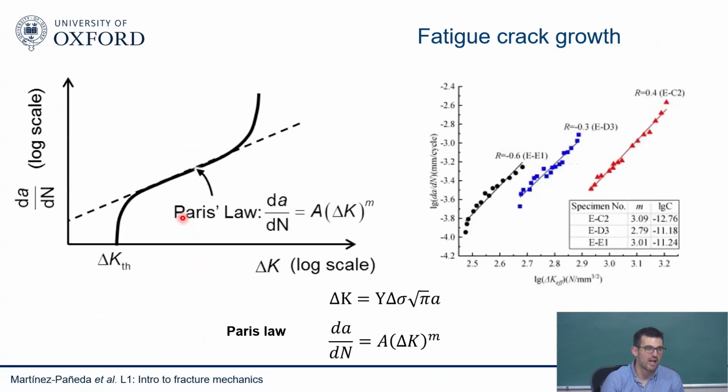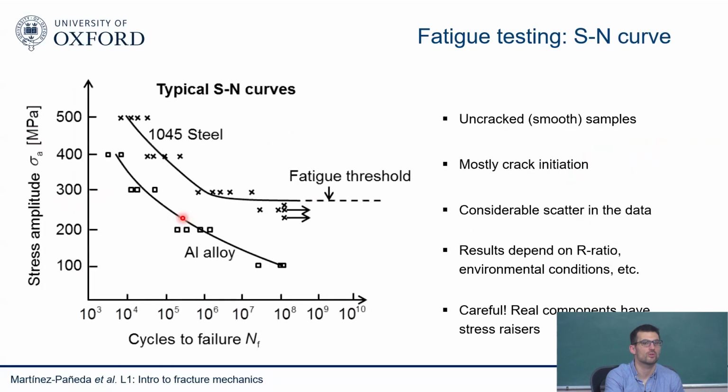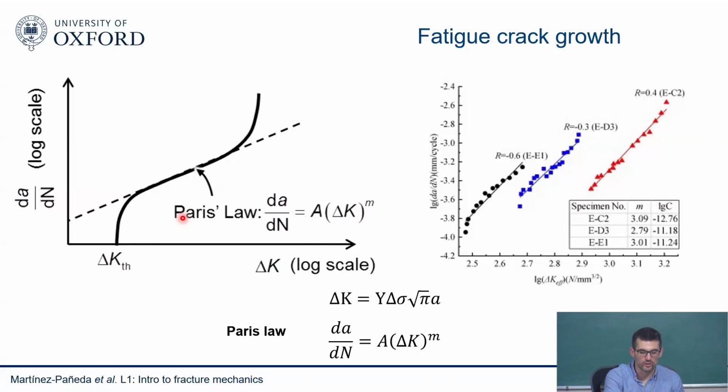And the last slide that I have before the coffee break: of course, we also deal with fatigue crack growth. So this is the total life approach, mostly dealing with crack initiation, which is arguably the least understood part of fatigue. It's very microstructure dominated, more complicated, maybe more scientifically exciting, so to say. The fatigue crack growth part we know more or less. This still remains a bit empirical, but Paris law does describe the data quite well.